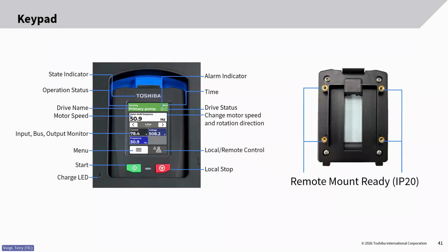And as you can see, it's IP20, so NEMA 1 mount ready. You don't need any extra external kit. You just line up the mounting holes and attach it to a panel.